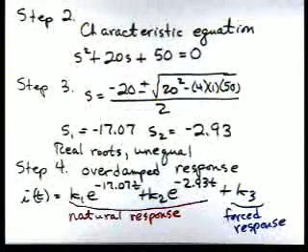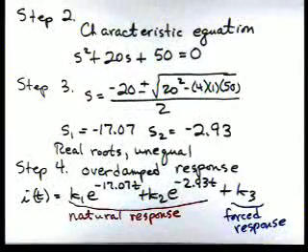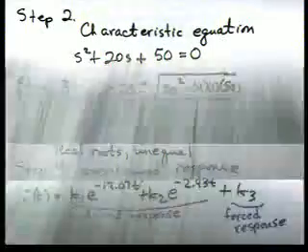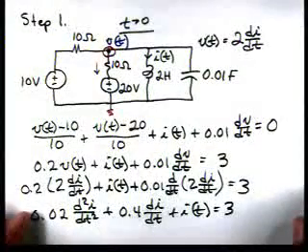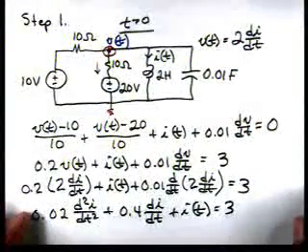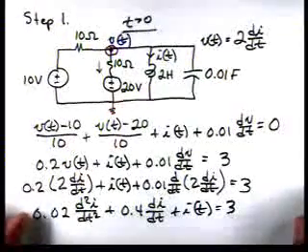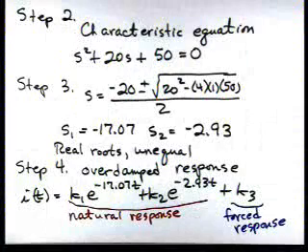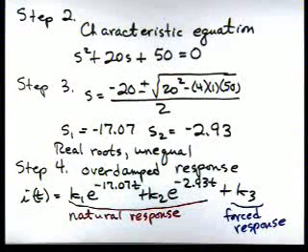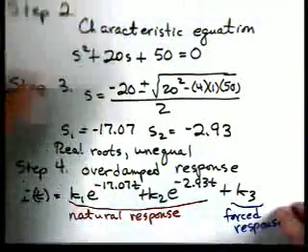That's because if we look at our circuit for t greater than 0, we notice there are going to be sources left in that circuit, and as a result, we'll have some value of DC current flowing at the end, and that's going to be the K3 term. So now, our challenge is to go through and find values for K1, K2, and K3. So here we're at step 5. Let's now start at t equals 0 minus.